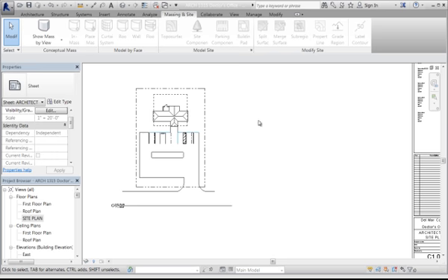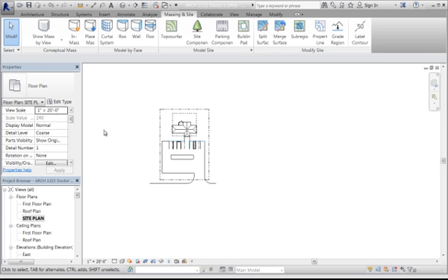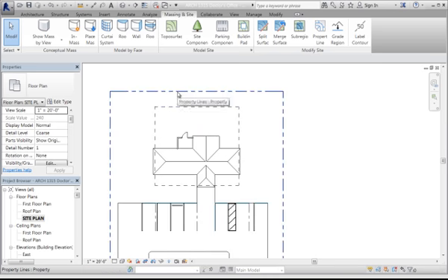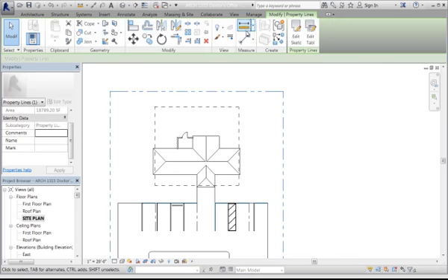Now you've got to dimension it all. So back to your site plan. Your property line, since you made it up, I want you to write it the way it's written in the book, because that is how it's written. On that page where I showed you, like, south 53 degrees, 28 feet east for 115.83 feet. So first you have to figure out how long that is, and you can either measure it like this.